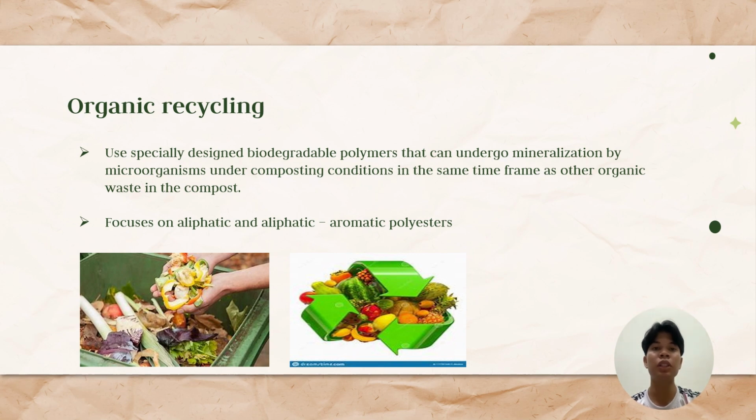is a commercially available polyester that shows 75% biodegradation in industrial compost in 8 weeks that increased to more than 90% in 12 weeks. Like PBAT, the ester functional group in several other aliphatic and aliphatic aromatic polyesters has the capability of undergoing biodegradation under industrial composting conditions.